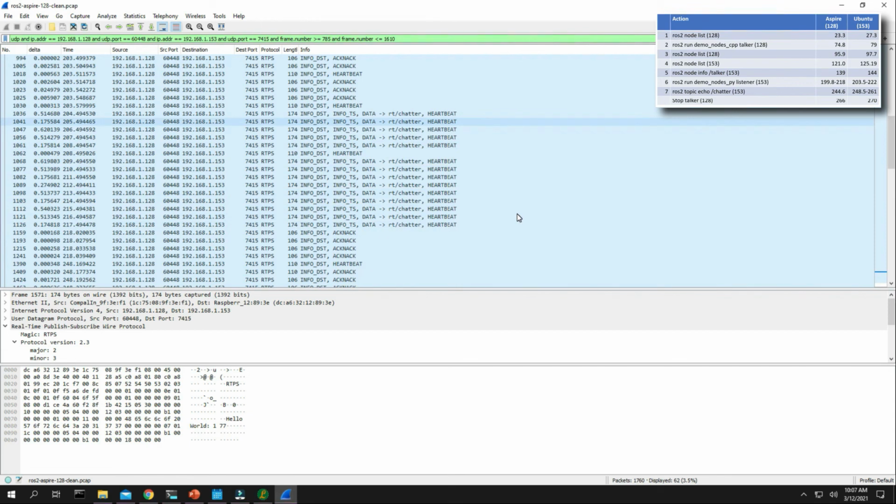So the interesting thing is, compared to ROS1, it's quite a nice protocol, a lot more complicated, especially because things aren't so much in plain text with RTPS, so you really need the decode to see what's happening. Makes it a bit more compact. It's nice that it's using the built-in multicast capabilities of IP networking. The other note here is this is running under UDP as the overall protocol.